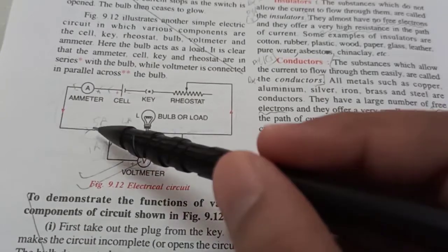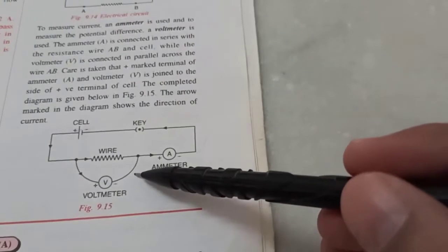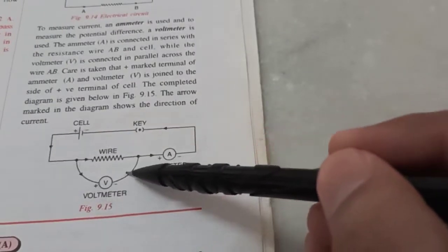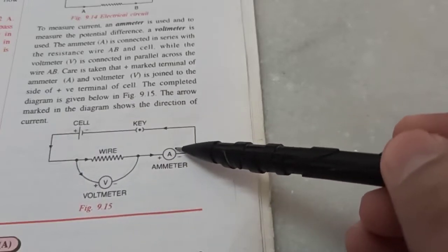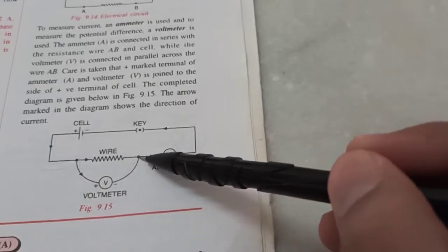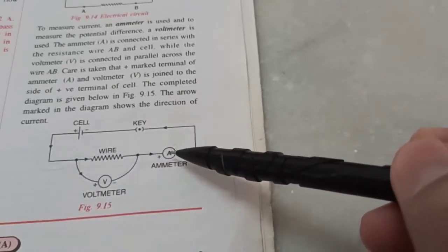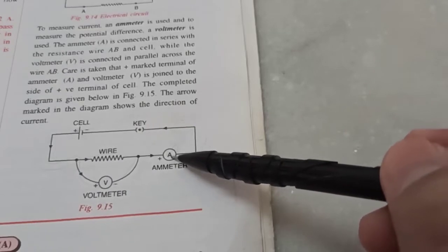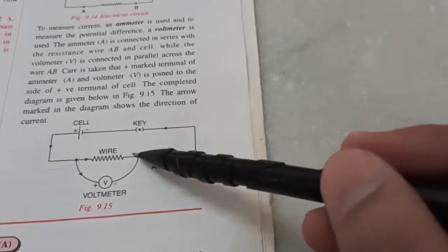There is always splitting of current. Even here, if you see, the voltmeter is connected in parallel, not mathematically parallel, but it's just that the current is splitting into two paths. Whereas the ammeter, which could be connected anywhere, here, it doesn't matter, the entire 5 amperes will pass through the ammeter, and that is why the ammeter should have very low resistance. We don't want the ammeter to create more hurdles for the current in the circuit.